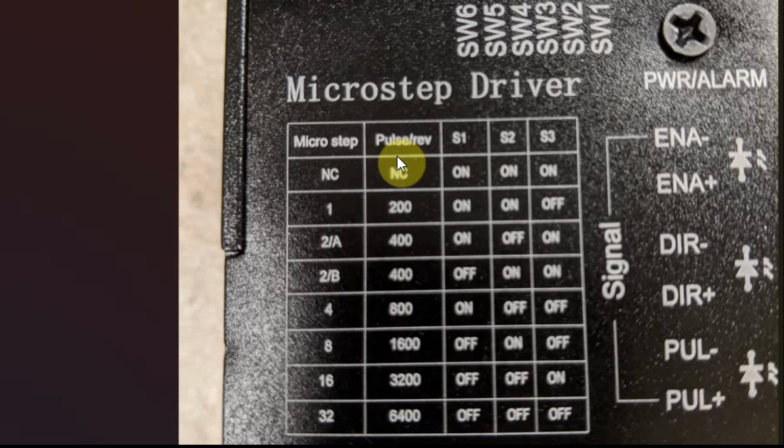And I'm using this type of controller right here, one of these black boxes that you can buy on Amazon all over the place. I'll put an affiliate link to that in the video also. But I have 3 pins, which are enable, direction, and pulse, or clock. I call it clock, but it's just a pulse. When you go up and down, it triggers the stepper to take a step.